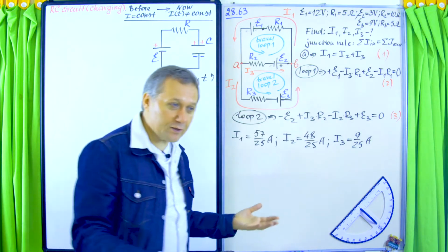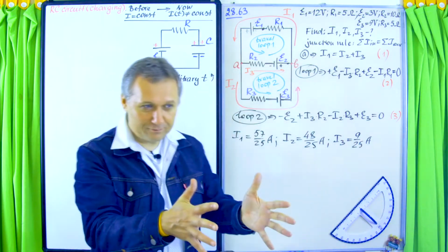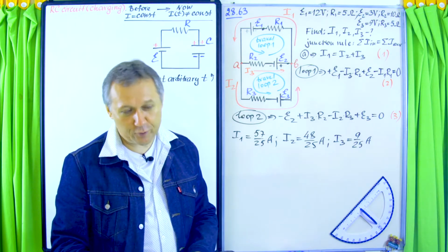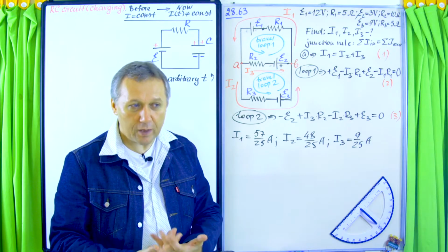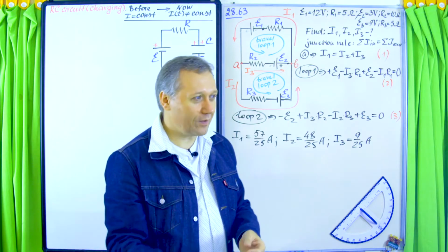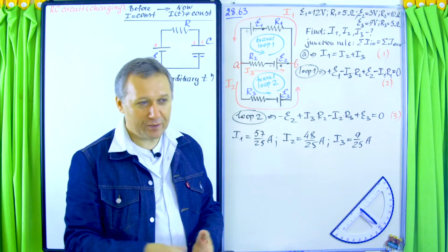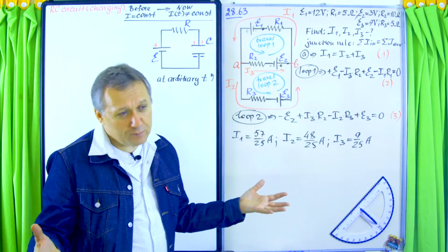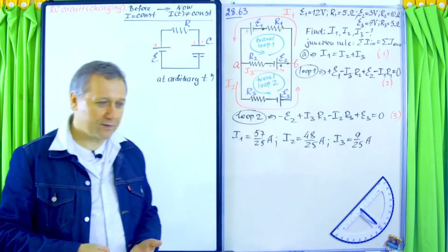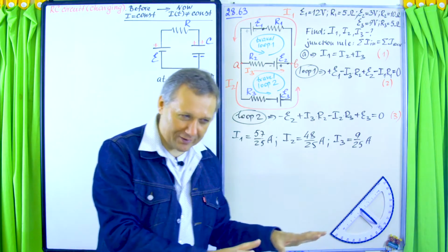Then, the second situation: what if your capacitor is already full and you want to discharge it? You're going to discharge it through the resistor. Why? Because if you just connect the plates of the capacitor directly, pretty much without any resistance, most likely you'll just damage your capacitor and create lots of mess. So it's better to slow the discharging process down.